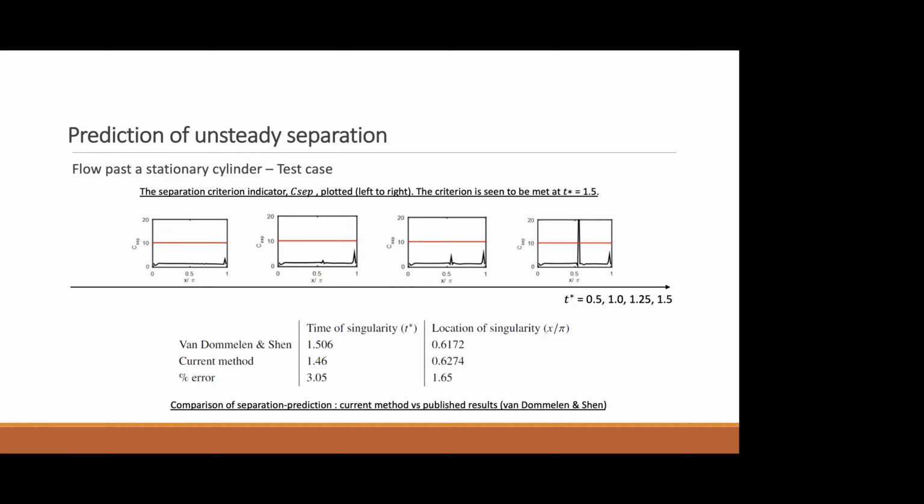But we are seeing that this viscous-inviscid interaction and the boundary layer solution are quite sensitive, and everything needs to be done quite accurately and to second order in order to get converged results and for the solvers not to blow up. So we haven't yet gotten to the stage where we're able to fully do this separation and reattachment. But I am hoping that if things are done carefully and using second order methods, we will be able to do it. But yeah, it is numerically challenging.